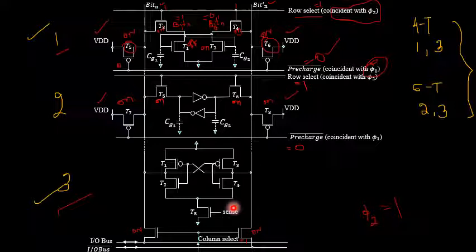the current flowing from VDD through an on transistor helps to maintain the bit line state and predetermine the state which will be taken up by the flip-flop, that is this particular sense flip-flop. That is the working operation, what is going to occur in case the sense signal is equal to a logical 1 state.